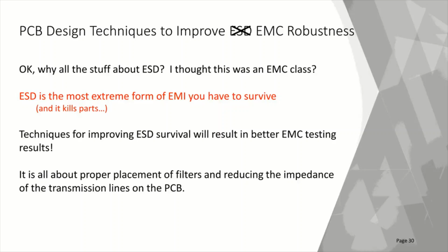If you do a good job with this design philosophy, then as I said earlier, you're going to probably have a product that's more robust and will exceed its behaviors in the expected environment, in that it can be able to withstand a more harsh environment, because your customers are going to do everything they can to be mean to your poor little products. And it's all about how do you manage the copper and how do you manage the special components that you may be forced to use in order to allow your product to survive in the environment that it's intended to be used.